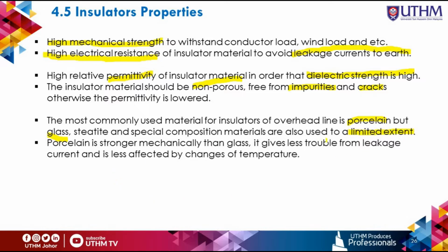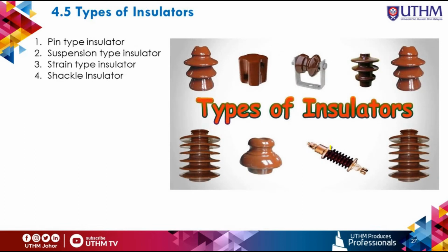So why is porcelain used? It is because porcelain is stronger mechanically compared to glass. It gives less trouble from leakage current and is less affected by changes of temperature. So there are 4 types of insulators.